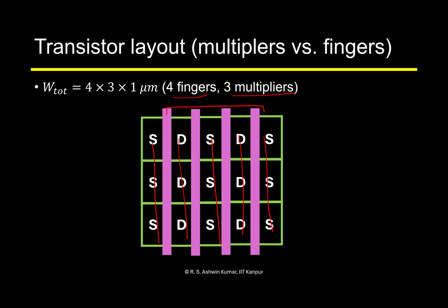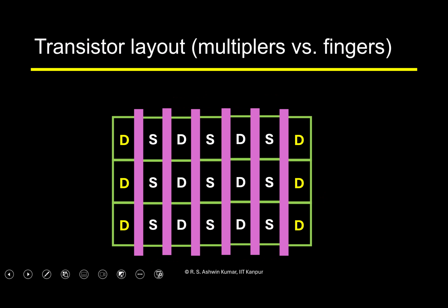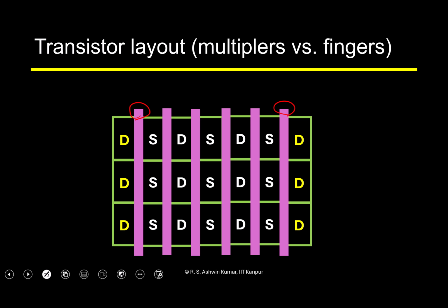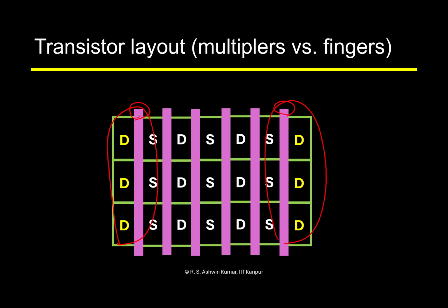And whatever we saw in the first half still holds good. The transistors at the corners will feel bad because they don't have neighbors here. So what do you do? You put dummies and introduce neighbors for them, something like this. What I have done is, I had 4 fingers here, and now I added 1 finger on either end. So this is now your dummy transistor.